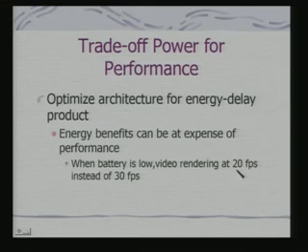And if they are operating on a battery, if I have the battery condition monitoring circuitry in the embedded system, then what can be done? The video rendering, instead of at 30 frames per second, I can reduce it to 20 frames per second. So, really what will happen is your battery life is increased, but you really are not suffering in terms of performance when it is a soft deadline.